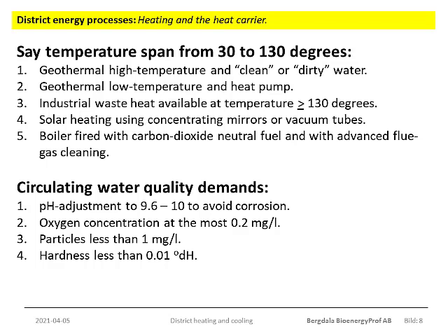Most common is to reduce the amount of salts, again to be safe from corrosion. And then there is often a need of softening, which means that the amount of dissolved calcium and magnesium should be reduced. So, deoxygenation, ion exchange units and demineralization will be needed, and then a pH adjustment. And there must also be a similar cleaning system online, so that eventual makeup water meets the same quality demand in the case of leakage.